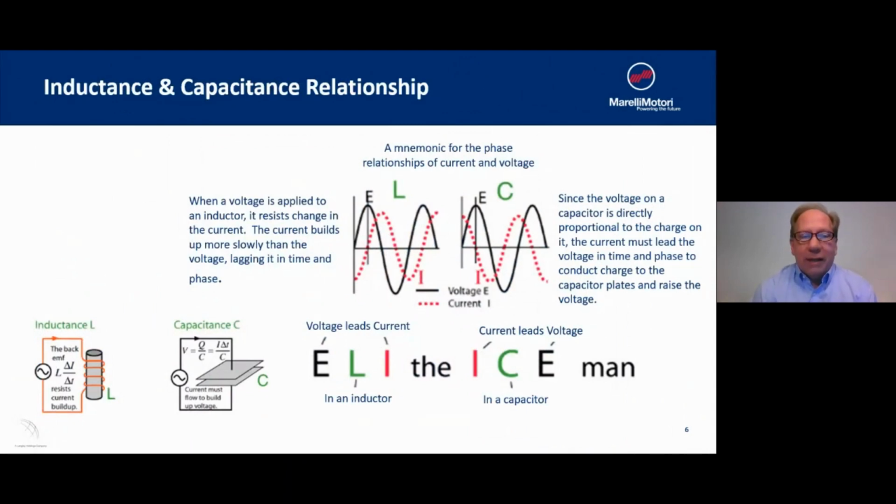Next, let's take a little look at the inductance and capacitance relationship. I show this because this is often hard to visualize. When you use a simple clamp-on electric meter or amp meter or handheld meter, you're not seeing this relationship. But when we have inductive loads, the voltage leads the current. And this is an explanation as to why. But it pulls it out of phase. When we pull the voltage and the current out of phase, this refers to our power factors, that relationship there.